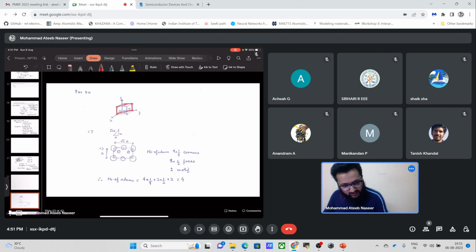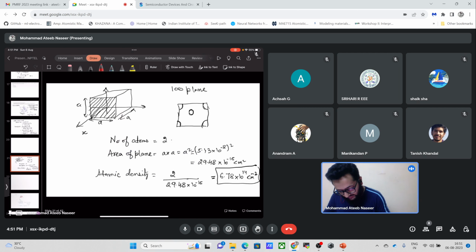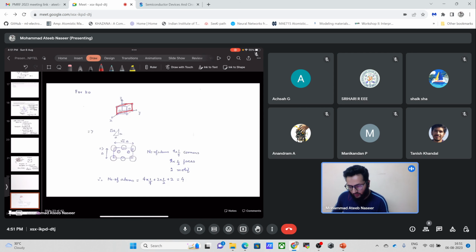Similarly, in the previous case, when we studied the 100 plane, we saw that it just intersected the x-axis and not the y and z axes. So whenever we see a 1 written, it means that it is intersecting that axis. So this 110 simply means that we are intersecting the x and y axes respectively.